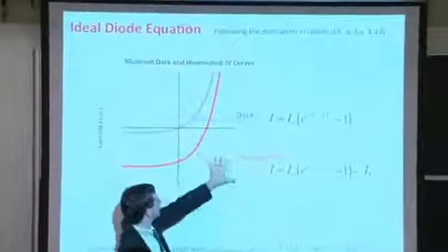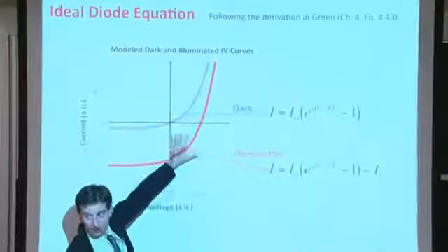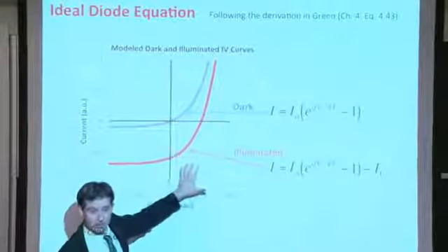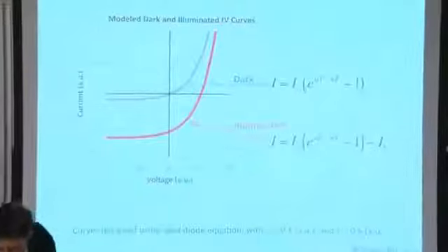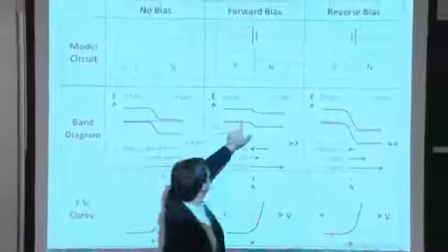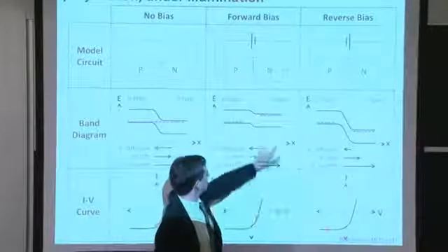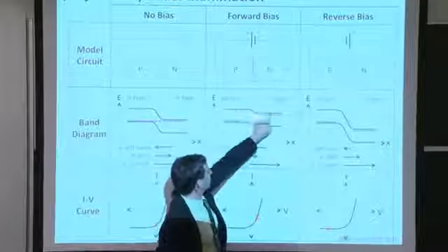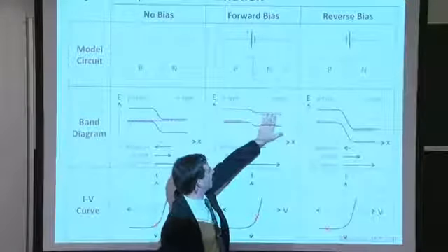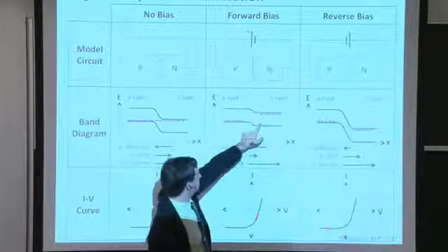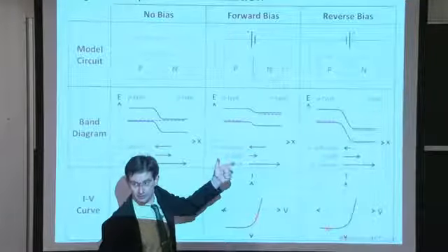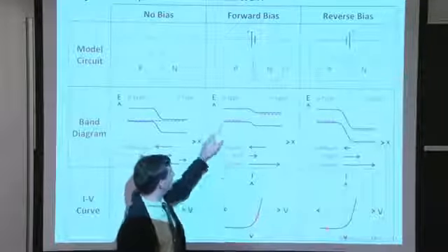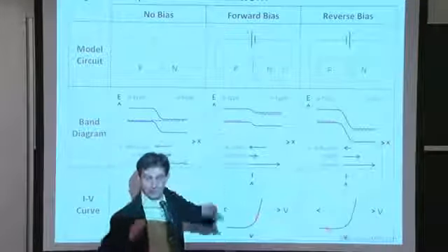And we're focused on this fourth quadrant right here, because this is the quadrant in which power is coming out of our solar cell device, usable power that we can use to power an external load. Why? Well, first off, the voltage is such that we can power an external load. We have charge separation. The electrons are accumulated over here, and they have higher potential than they do on the other side, which means that there is an incentive for them to go through the external circuit, deposit their power across that external load to get back to this other side where their potential is lower.